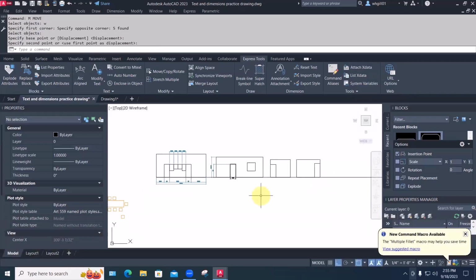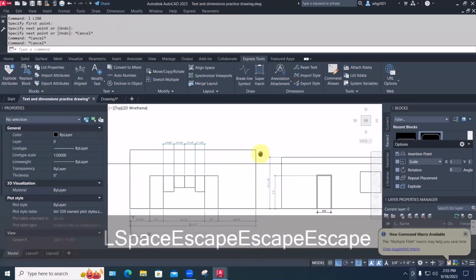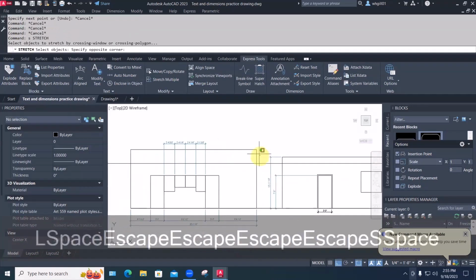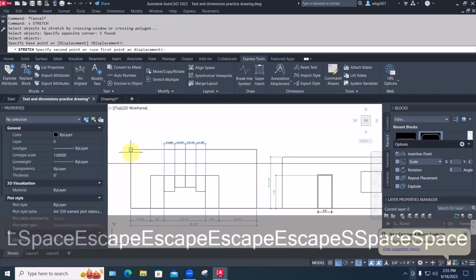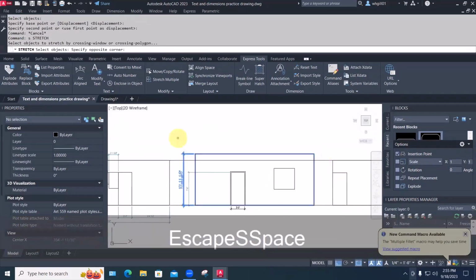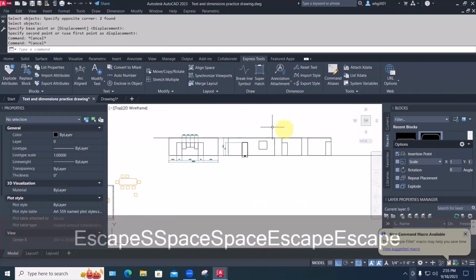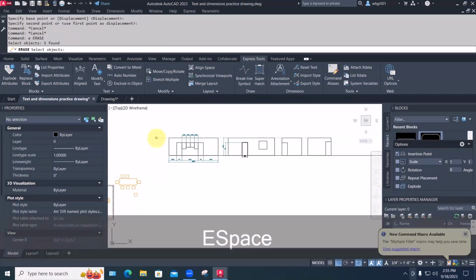Like that. And then I see all of a sudden, I know that's one room, but I've got 3 different ceiling heights. Which one is it? At that point, you might decide it's this one. So I might draw a line from here to here, and then use the stretch command, S for stretch, to grab all those and bring them down. Grab all these and bring them down. And then since I've got them lined up, I can get rid of my guidelines.